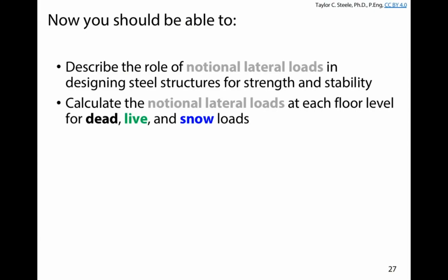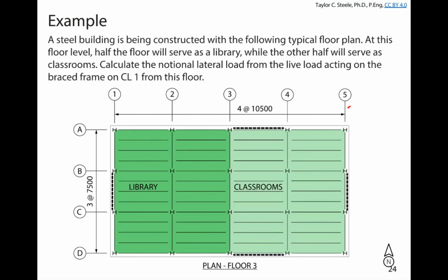The example notes for today's lecture include what I did here today, but they also include for our example building all the steps. So live load at each level, dead load at each level, snow load, roof live load, and it shows you how to get those forces and how to apply those loads to your free body diagram of your truss at each level along with the gravity loads. Okay, so go through that example document. Come see me if you have any questions.